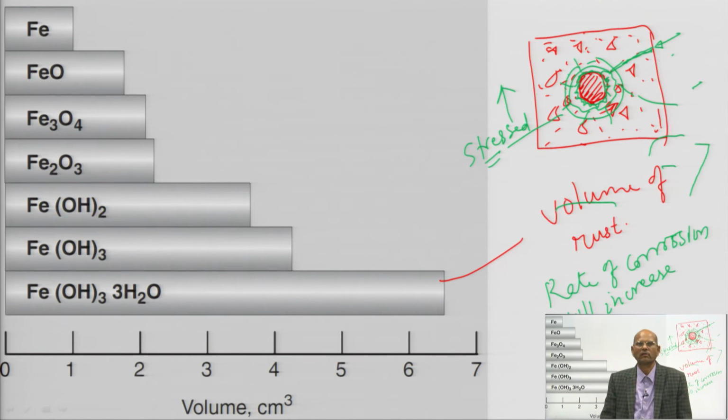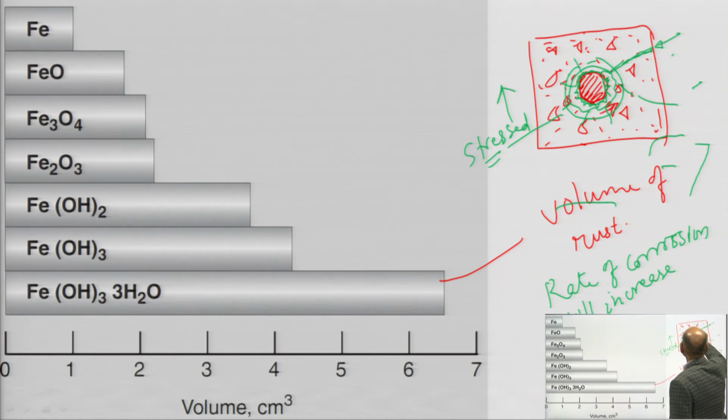Suppose your structure has shown signs of cracks after, say, 10 years. Do not think that further cracking will take as long. It will take less time and increase further, and finally, within another 3 to 4 years, the complete structure may not be fit for use. It may collapse also. So, this is what we have observed.